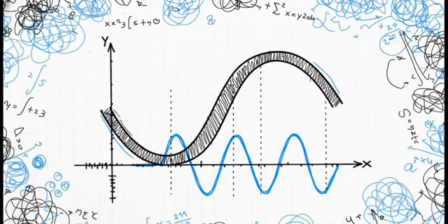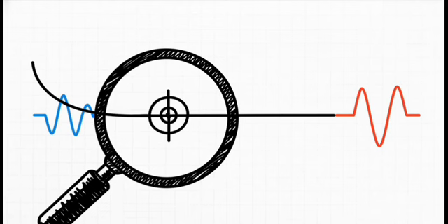Well, if you're dealing with really big signals that swing all over the place, then yeah, you're stuck with that messy curve. Trying to calculate gain in that situation would involve some pretty hairy calculus. It's not fun. It's really complicated. But here's the trick. It's an absolutely genius move. For the small signals we're usually trying to amplify, we don't care about the whole curve. We only care about what's happening in a tiny little area right around our Q point. And if you zoom in really, really close on any curve, what does it start to look like? A straight line. Just like that, we've linearized the problem.